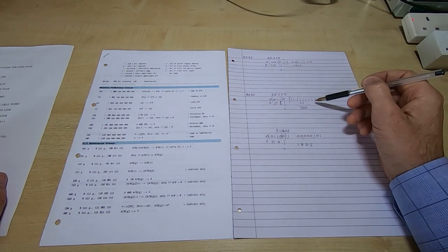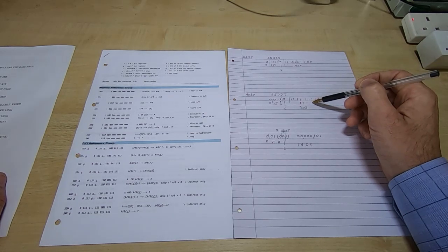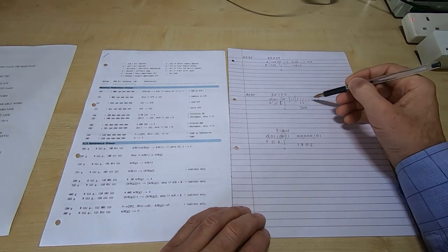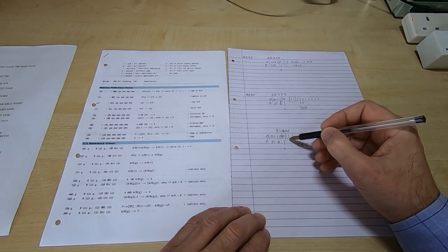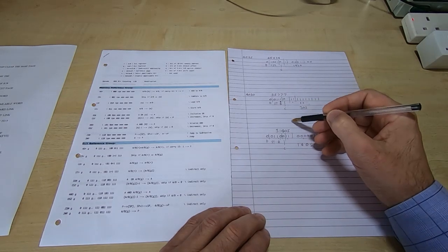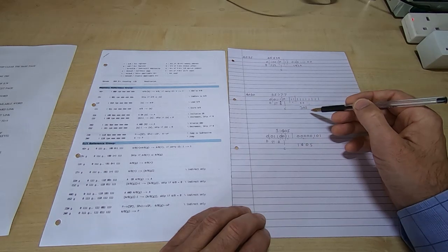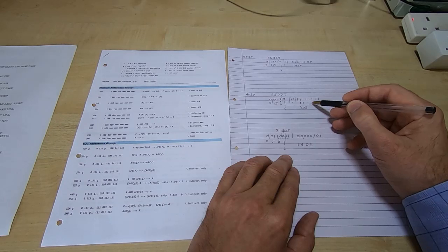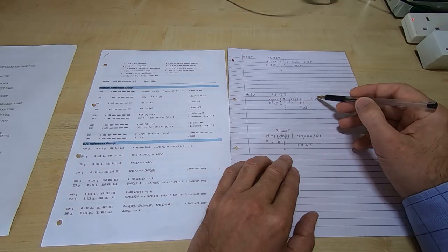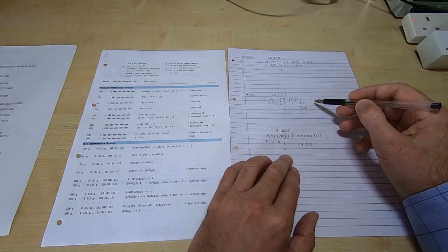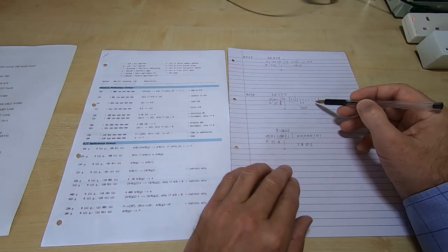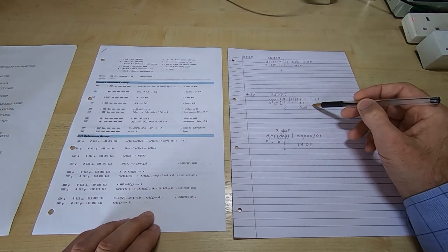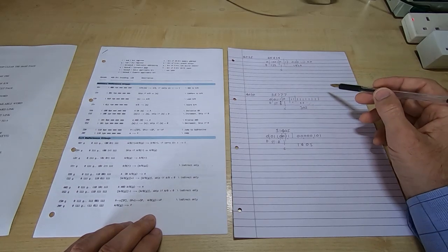Normally it indicates a failure mode for the device, and also if you bear in mind these are 8-bit ROMs, you'll see that these 2 bits are correct in both addresses. So the top 2 don't look too bad, whereas the bottom one should be this and it's giving us this, so it looks like that particular ROM has failed completely, or at least on this byte. I have done this for several other addresses.